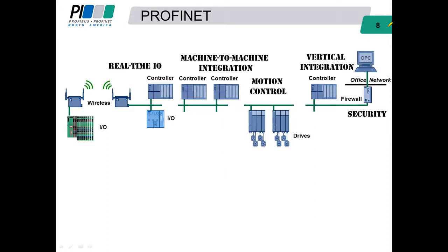Sometimes people think that OPC might be replaced by, for example, the machine-to-machine integration function of PROFINET. That is not the case. OPC typically resides in a computer somewhere, either a computer-based HMI or some kind of computer-based system up in the office.